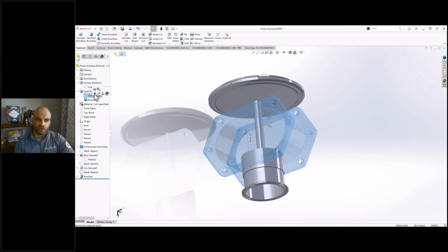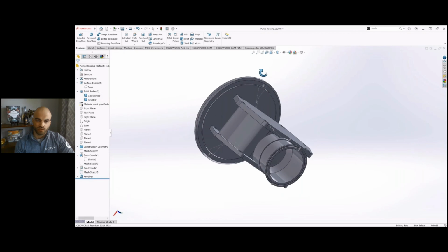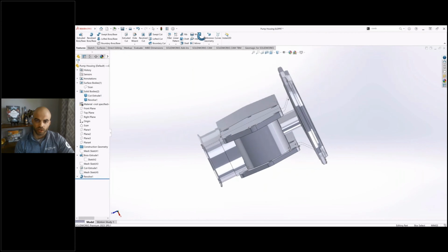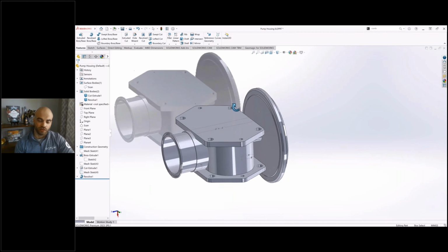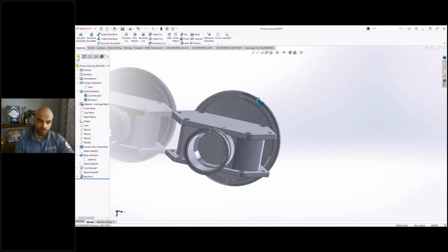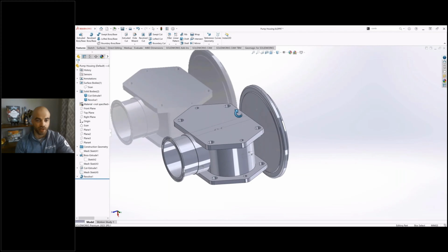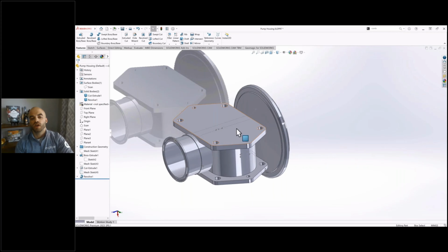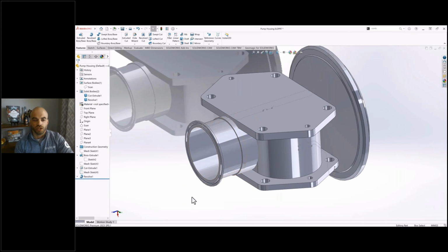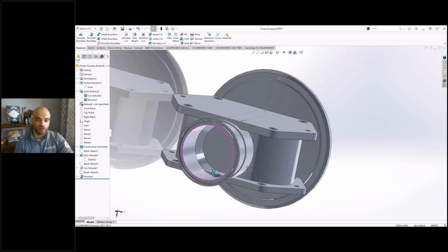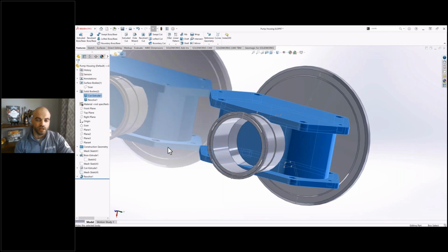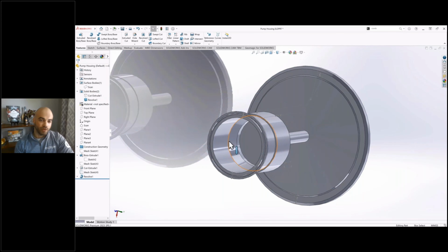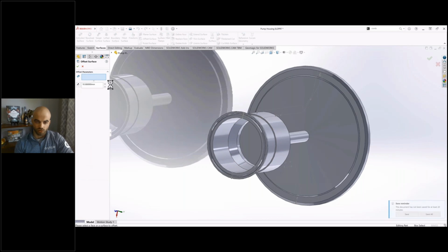So finishing that sketch and revolving it, we've got our revolve feature, right? And we're starting to look a little bit closer to the final product every step of the way. Here, I'm noticing that there is some geometry inside of that pipe diameter. You can see right there, that sharp edge from the flange that's poking through. And that's obviously not geometry that we want in the final product. So I'm going to do a little surfacing trick where I grab the inner surface of that pipe, copy it, and use that as a tool way down the line at the end of the workflow in order to trim that away once we do our final boolean.